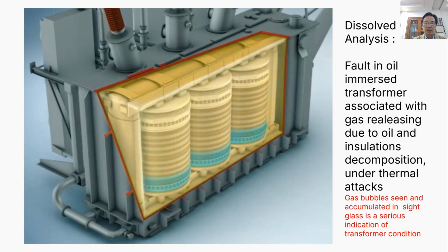We can have abnormal conduction, or even arcing. All faults are always associated with high temperature. Then the thermal fault is always associated with gas generation.